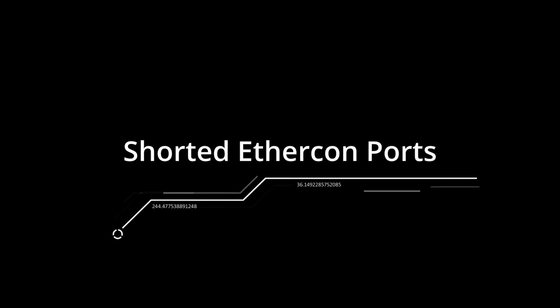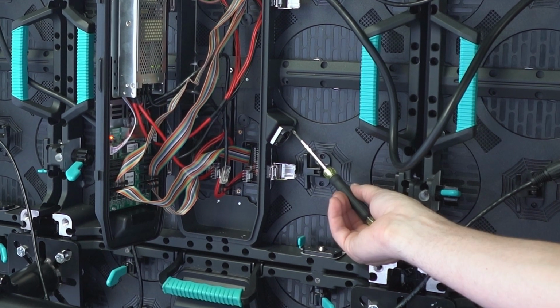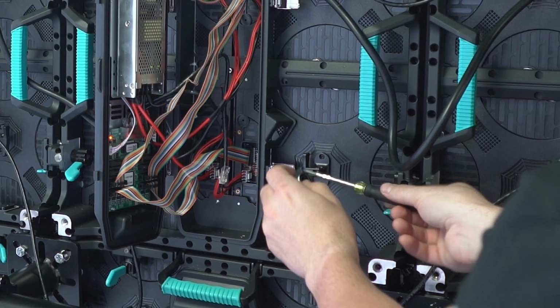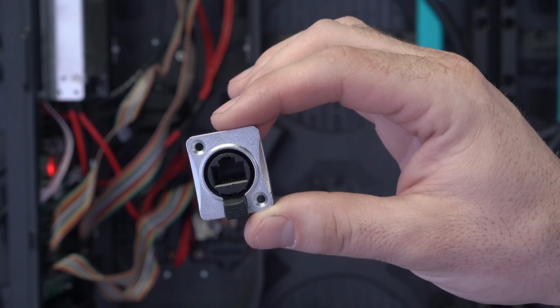Shorted Ethercon port. If the Ethercon port is damaged, replace one of the signal connectors by removing the 2 screws that hold the connector to the chassis. Then disconnect the internal Ethernet cable and replace the part.